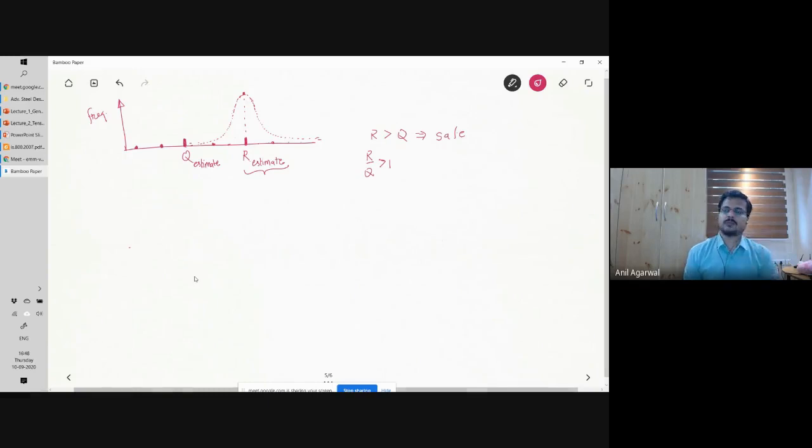Okay. Now, a similar thing can be said about the loads. So, for example, let's say I'm working with the dead load. I know the density of concrete, I know the density of steel. So I can calculate the dead weight of a building with decent accuracy, and I know how much dead load I'm going to get from a building. But what may happen is that maybe 90% of the buildings will be very close to that value, but still there will be 10% which will be slightly away. Maybe I'll underestimate, maybe I'll overestimate. So here, for 90%, the plot should probably go a little higher.